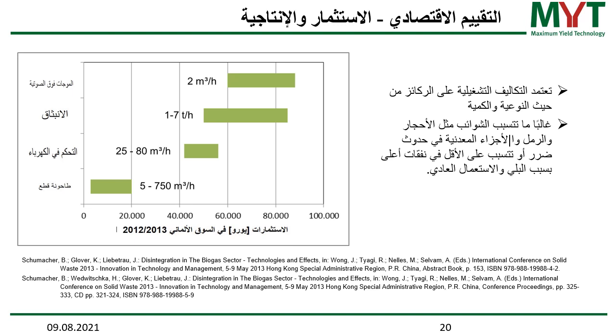So really check on the quality of a substrate before looking into operational costs. And in particular, stone, sand, pieces of metal, this can quickly destroy your pretreatment technology if it is sensitive to this.